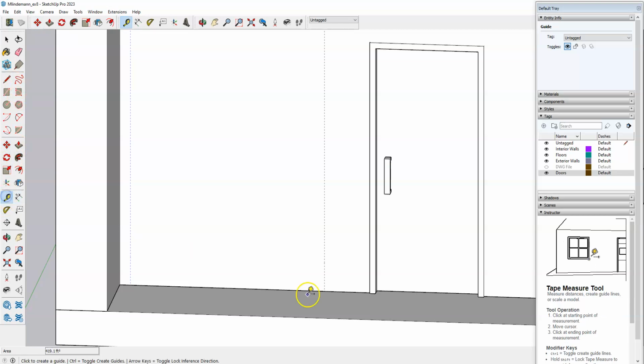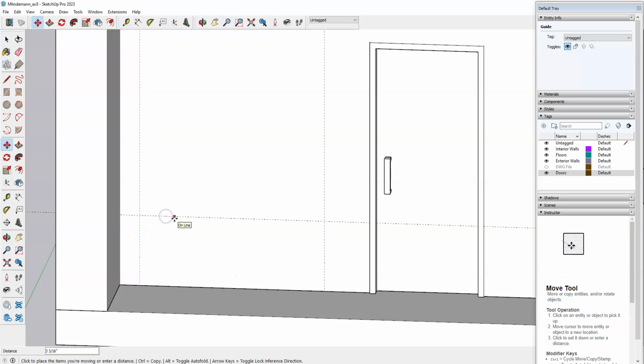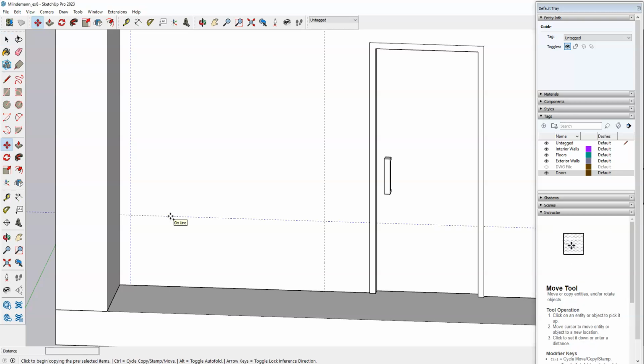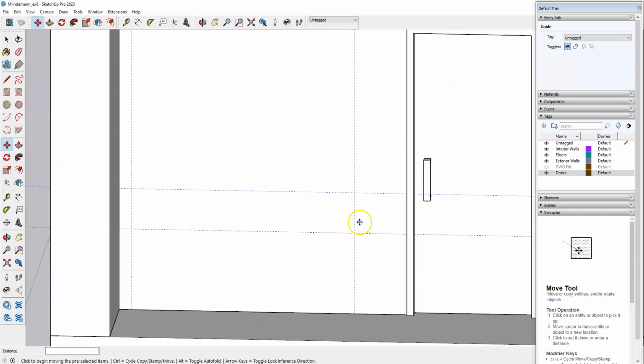And then let's create another grid line from the bottom edge here. And it was 2 foot high. So 2 foot, enter. And then I will copy that 1 foot above that grid line. And so now this should be our opening here.